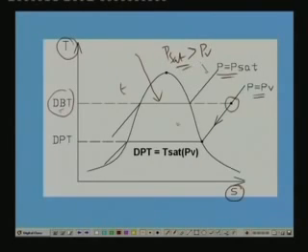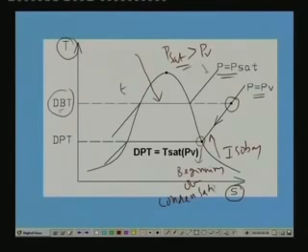Now, if you cool this water vapor isobarically, that means along the constant pressure line, so this is an isobar, its pressure remains constant, its temperature reduces, and you find that at a particular point the water vapor begins to condense. This is the point where the beginning of condensation occurs. This temperature at which the first drop of water forms is called the dew point temperature.